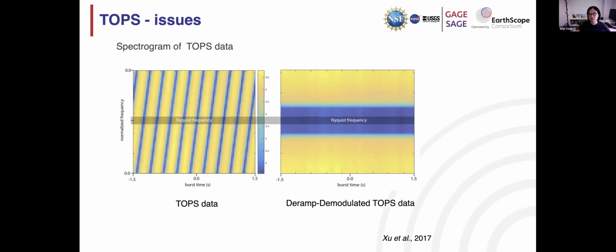Typically for traditional radar processing, we would like to have the data at a near zero Doppler rate. But that's usually okay because for Sentinel, they know how fast the antenna is steering. So we could correct this issue by a process called deramping, so that the data is as if we collected it at zero Doppler. This allows you to perform radar processing, like resampling, using the old way we process the data, and after that we can re-ramp the signal back. So that's issue number 1.